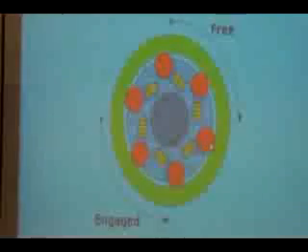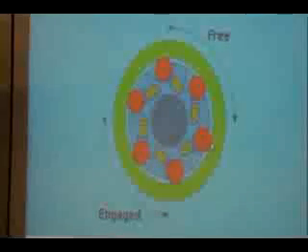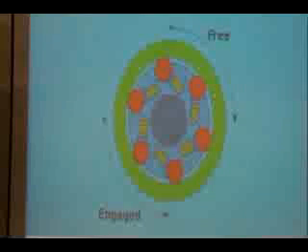Now in this figure you have, this is a rim. Here you have spring-loaded balls. These are springs. These balls are loaded by a spring. Meaning these balls will always be pushed out. They will be pressing hard against the inner surface here. Understood? You have balls here and these are loaded with spring, meaning these balls will be pushed out.